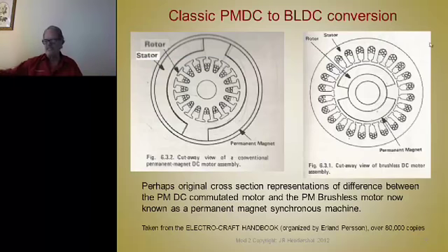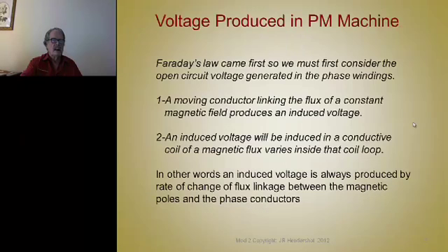If you drive either one of these motors, spin them, and look at the output voltage, you see what the back EMF is. It's very easy to see. You can't see the back EMF in an induction motor, but you can in these synchronous brushless permanent magnet machines. So that's where the terminology came from, as it was converted from an inside-out DC motor.